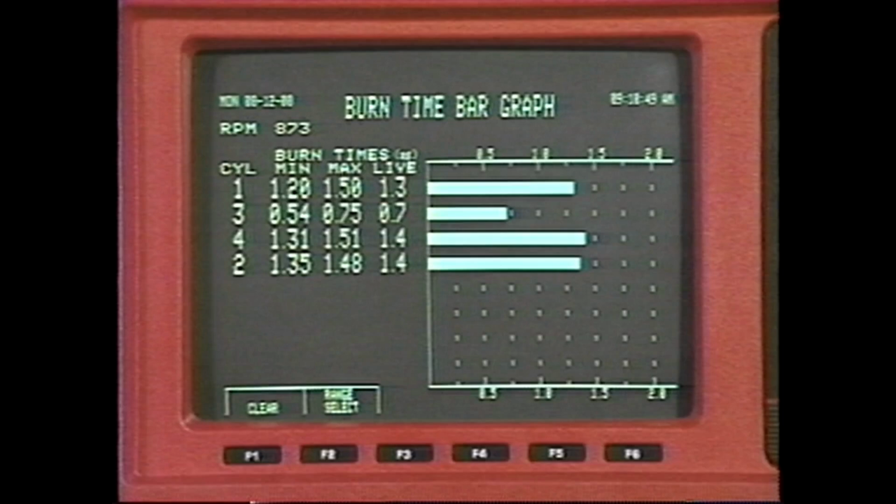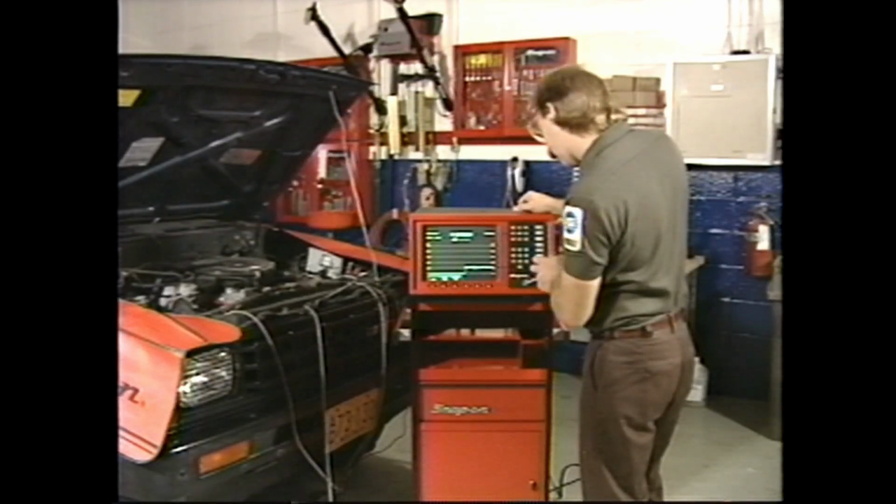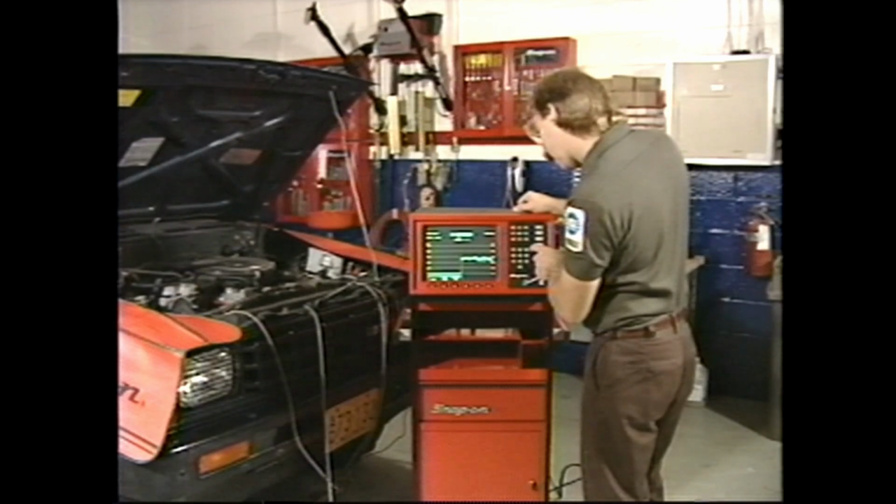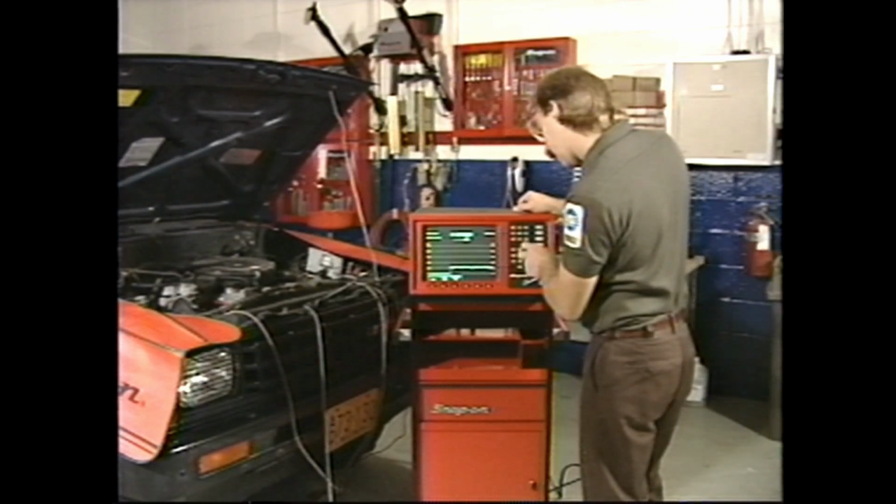With a high kV requirement and short burn time, we conclude that there's a problem affecting the secondary ignition system for cylinder number 3 that's making it difficult for current to cross the gap. A snap acceleration kV test and an underload kV test can help you pinpoint the cause of the problem. In this case, it's a high resistance spark plug wire.